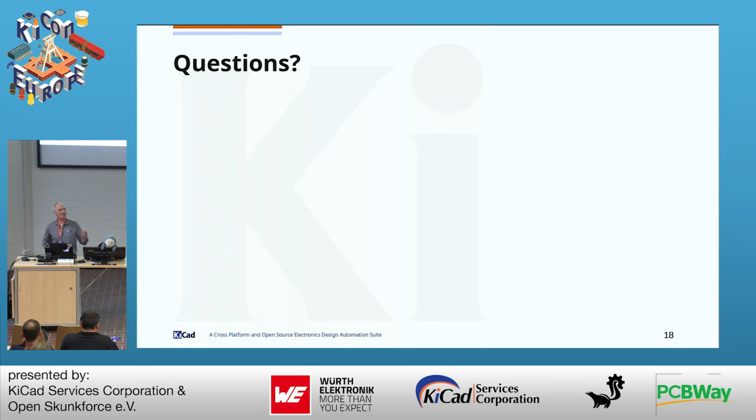But yeah, like I said, anytime you have a mismatch between the schematic and the board, it's going to complain. The DRC is going to complain, hey, I got a footprint that's not in the schematic. It's just the way it's going to be. If you update from schematic and you have the option to delete footprints that aren't in the schematic enabled, that's going to go away. If you have a variant and you've accidentally deleted it, it's going to go away. But there's always the undo command too.